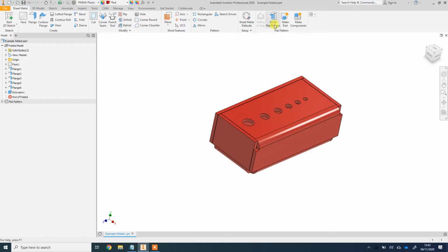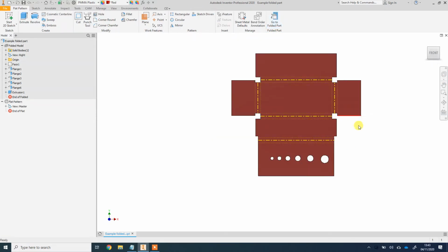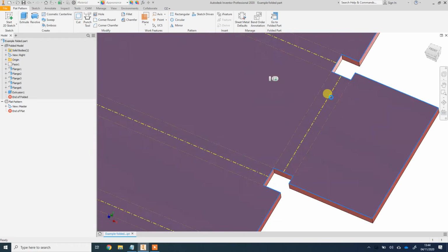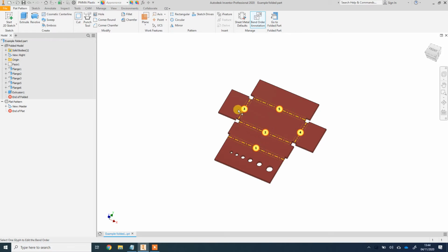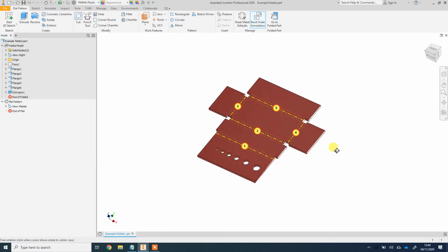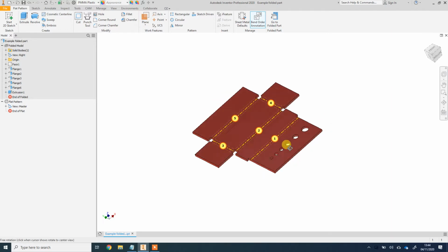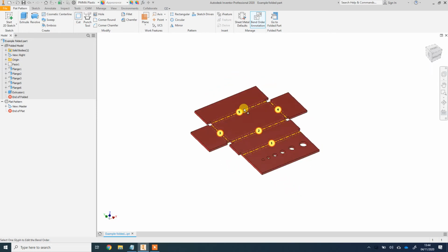What's really cool though, you can just click one button here, look, go to flat pattern, and then it will unfold your contraption into an outline that you could export to the laser cutter, and you can see exactly where you need to fold. And what's even cooler is if you click bend order annotation, it will tell you the recommended order to make the folds in. So number 1, number 2, 3, 4 and 5, because as we talked about in previous lessons, if you're folding up a 3D construction, you've got to think about the order you do the folding, otherwise it can all work out wrong if you get the wrong fold done first. So anyway, we're going to make this. Now, I'm just going to close that for now.